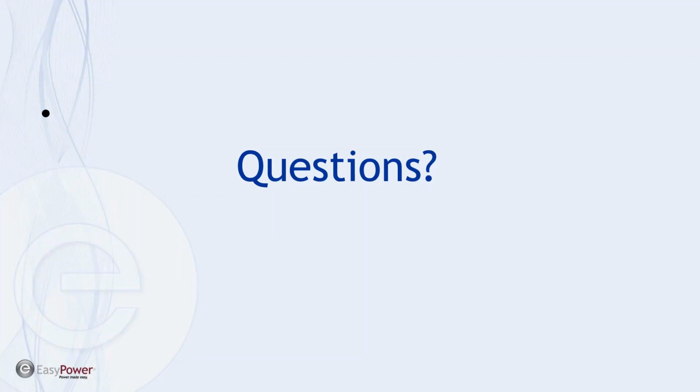And offline, I'm more than willing to talk to anybody that wants to talk about that and provide further discussion and substantiation. Here's another question. It says, why is it incorrect to provide PPE description on the arc flash label? Because it's a convenience to the electrician. I've been an advocate since I started getting into this that electrical safety programs shall be developed and implemented by the employer, and the label shouldn't stipulate the clothing. The electrical safety program should stipulate the arc flash and shock PPE, tools and equipment that the employer is going to specify and procure and provide to their qualified electrical workers, the qualified person, the electrician, right?